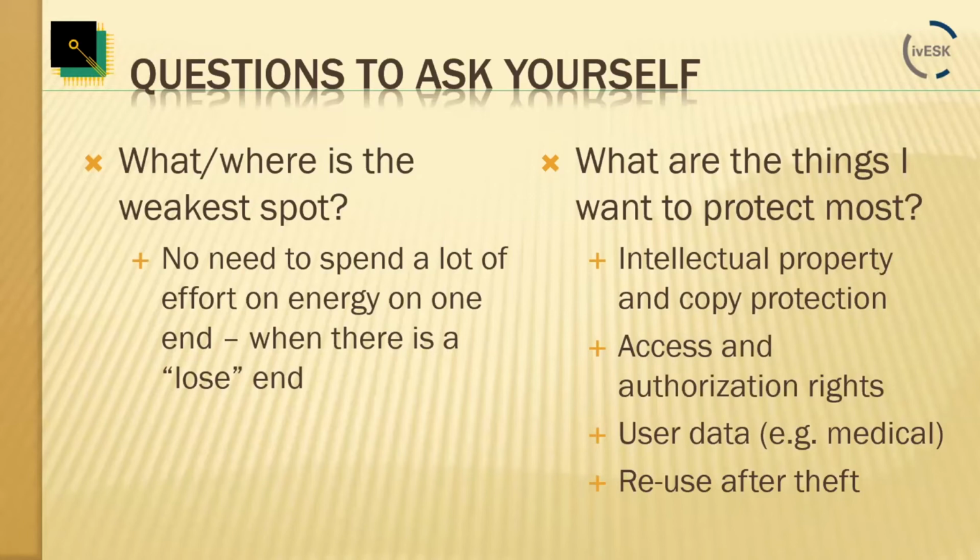existing CAN and CANopen bootloaders, we know quite a few bootloaders in commercial products that are as simple as: once they are activated, send them the hex file with the code, and they'll program it and go, with absolutely no security checks. Well, this is how systems were developed 20 years ago, and not even 20 years, even 10 years ago this was still more or less a common approach.